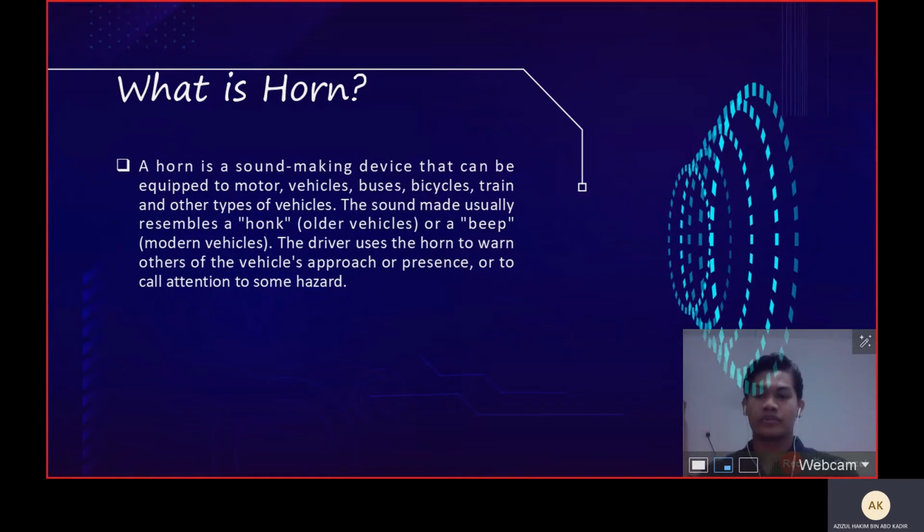The electronic horn is used on vehicles to give out a warning signal generated by an electronic circuit. A solenoid is magnetized and demagnetized to produce the fundamental frequency and cause the diaphragm to vibrate. This generates high pressure that passes through the trumpet horn to generate a sound. A key advantage of the electronic horn is the lack of wear, resulting in an average lifetime 10 times higher than with an electromechanical horn.